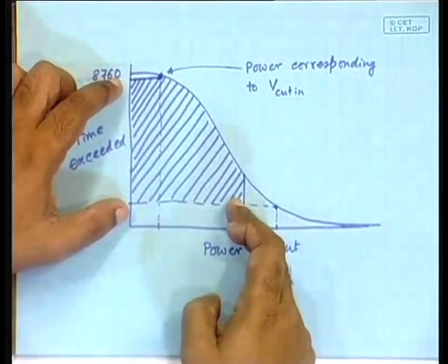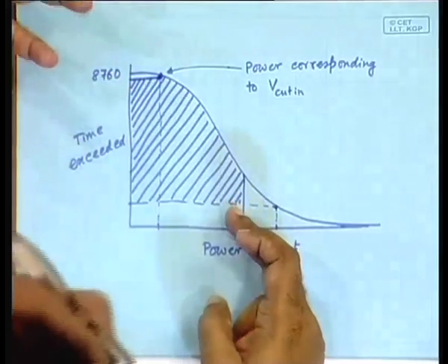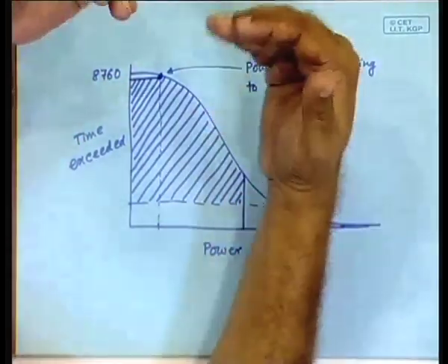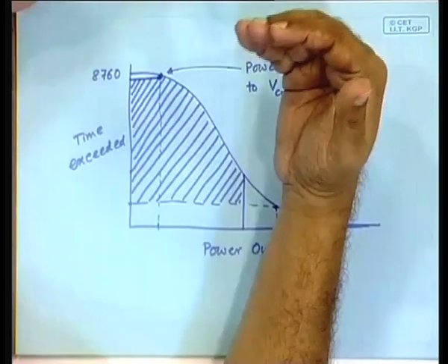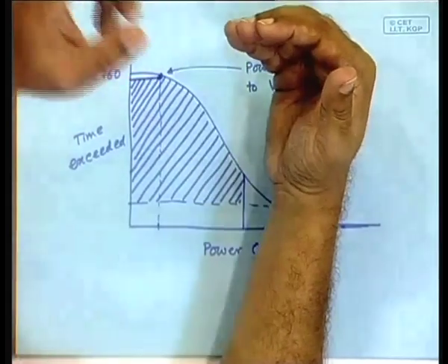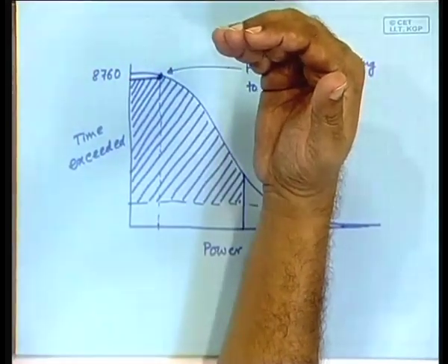The criterion should be how much area am I being able to use in comparison to something. In comparison to what? In comparison to the installed capacity, right. So, the bigger the wind turbine, there will be something in the denominator with which you compare. So, that denominator is the energy that you would generate if ideally the wind turbine is operated at its rated power for the whole year.